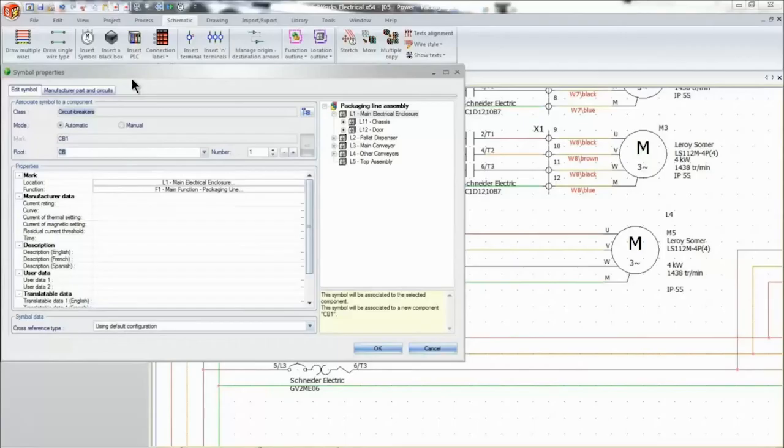First, we need to go ahead and add the symbol. So now we can look through all the symbols in our system. But if you don't want to do that, you can create something like a palette to search for symbols based on what you have. So you can search a description like 3-pole, for example. It'll bring up anything with a title called 3-pole. And you can just click and drag and put it into your schematic, and it'll connect all the lines just as you've added them, just like that. So you can connect it up just like that.